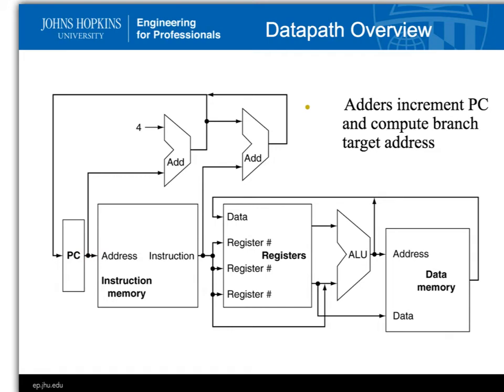Another thing to keep in mind when looking at these diagrams for the next few weeks: when we have a little item like this, that means this address is sent to 2 places. It's sent to the instruction memory, and it's sent up to this little adding unit. These little triangle-ish trapezoid things are adding units. So the address, at the same time, in parallel, is sent to here and to here. Up here, we add 4 to the address. This is where the program counter gets updated. These 2 things are happening in parallel.